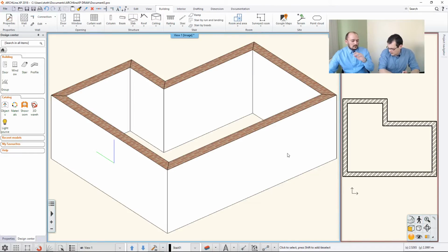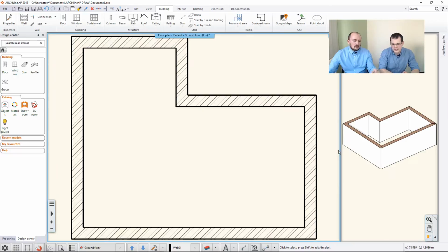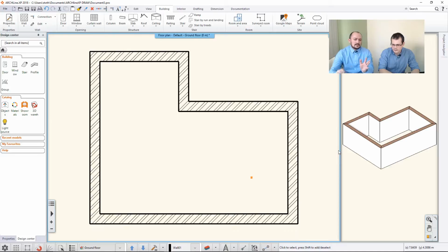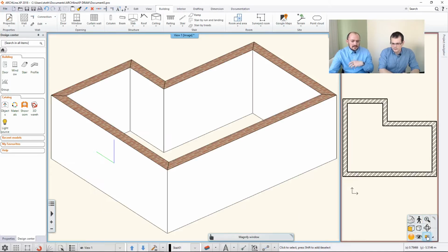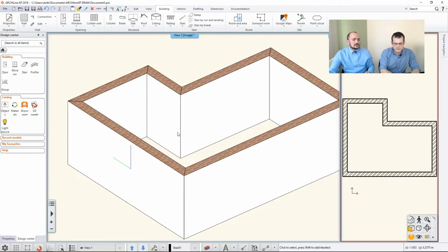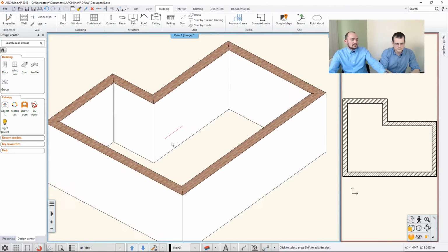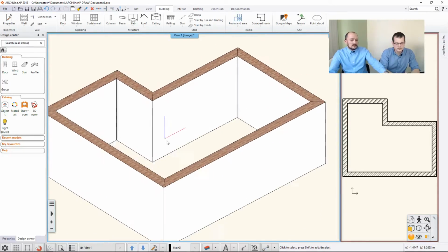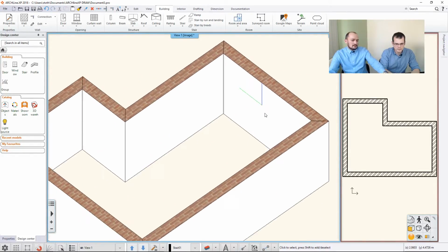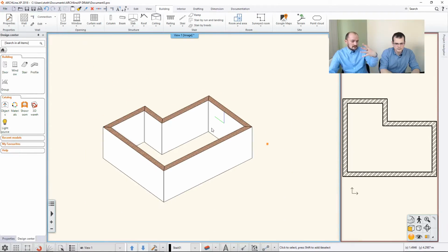What then? I see that on your floor plan there's some extra thing. Yes. Just to highlight it again, I click into the 3D and enlarge it. Then I can do the same thing as in 2D: zoom in, zoom out, and click, hold the mouse wheel and pan. And there's one extra thing, of course, which is rotation. For that, I hold the Shift key and click and hold the wheel, just as in the case of pan, but together with Shift it rotates the model around the axis where my mouse was. So this is how you can rotate this content.